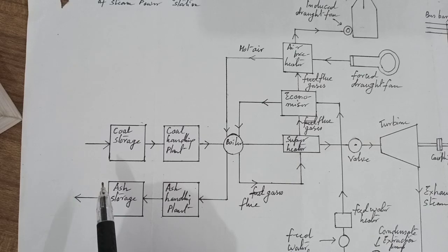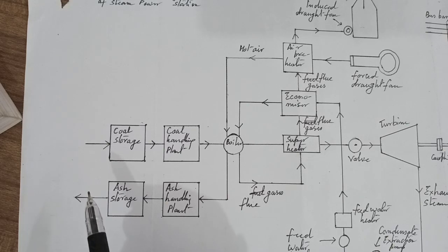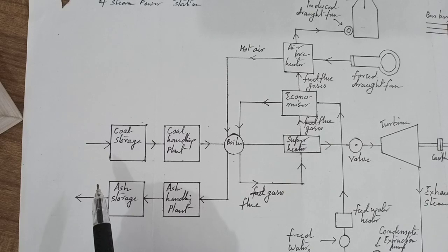Superheating provides two principal benefits. Firstly, the overall efficiency is increased. Secondly, too much condensation in the last stage of turbine, which would cause blade corrosion, is avoided. The superheated steam from the superheater is fed to steam turbine through the main valve.